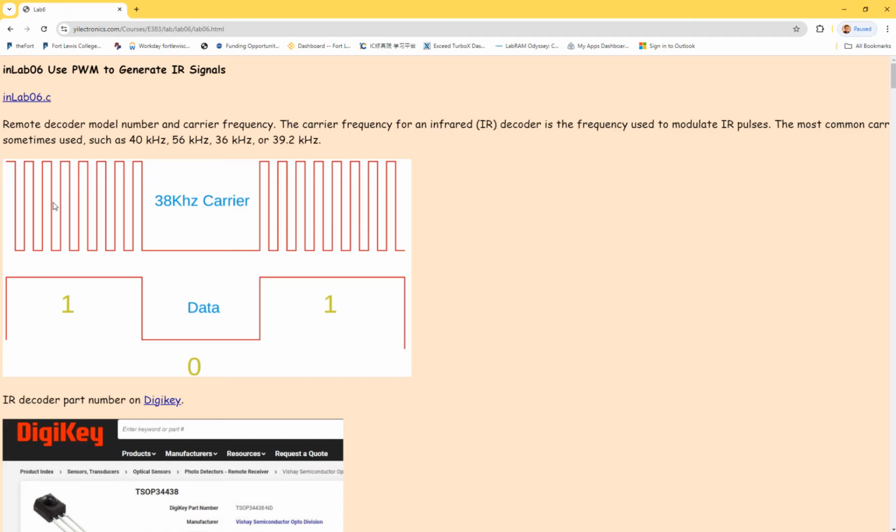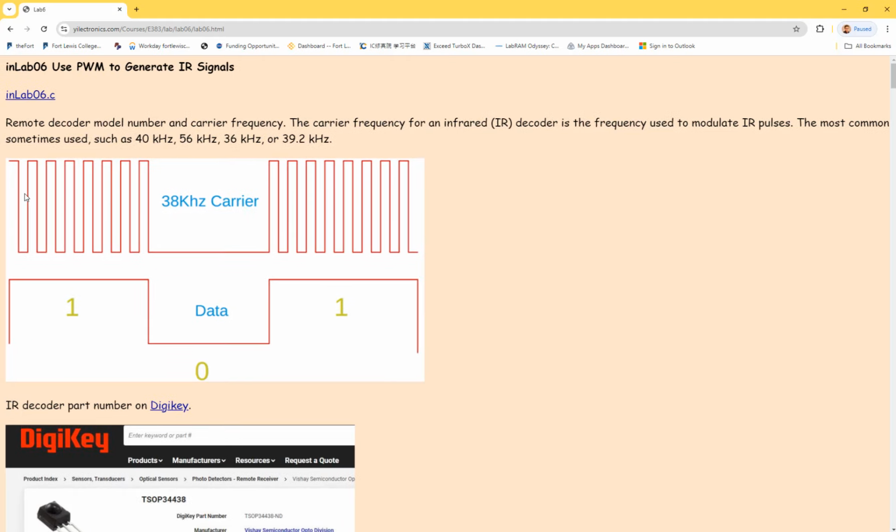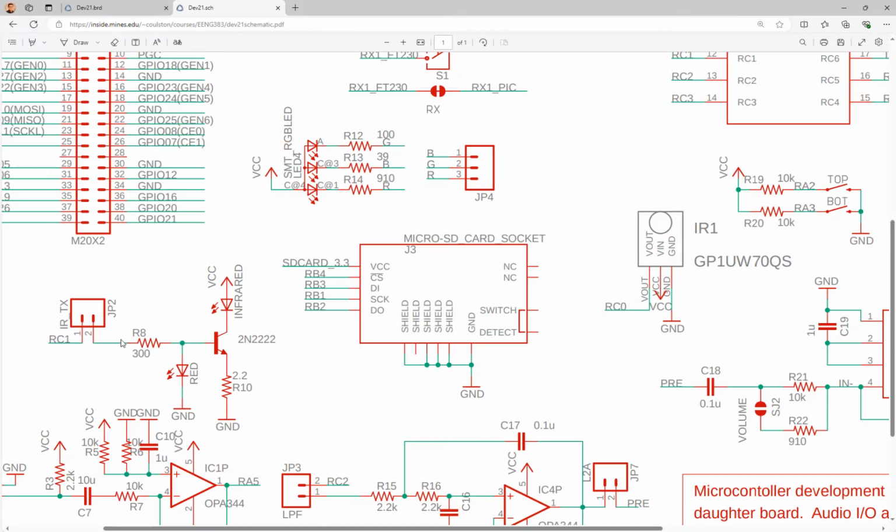So what about this? What is this pulse? Is it an electrical pulse or an optical pulse? Where is this pulse from? That's the electrical pulse from the sender, from RC1. So this is driving what? Driving the base terminal here. You put a jumper here, it's going to drive it. And then you get an optical signal.